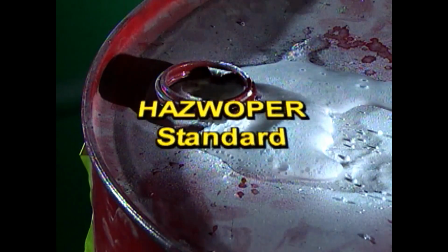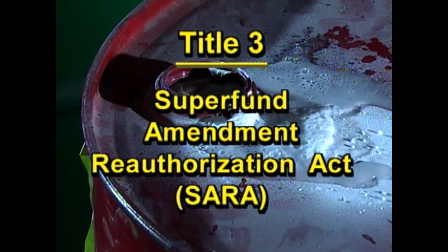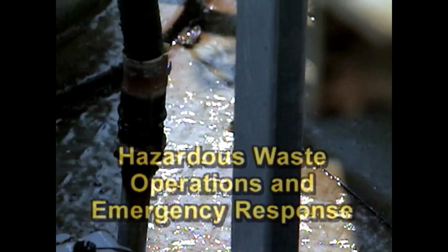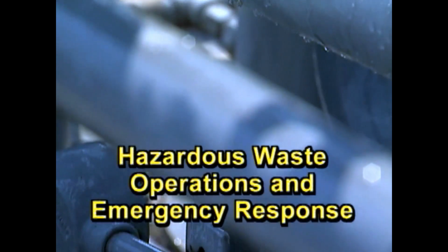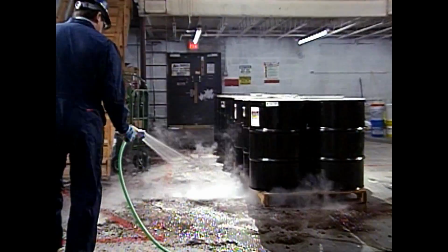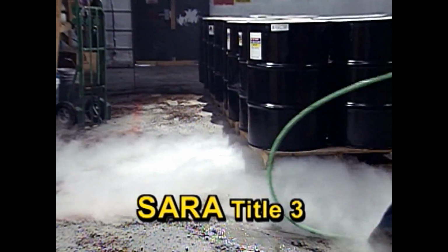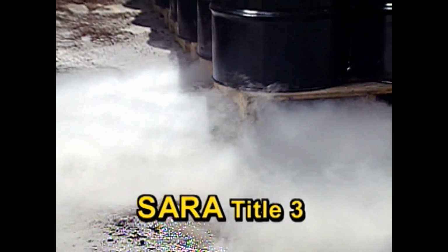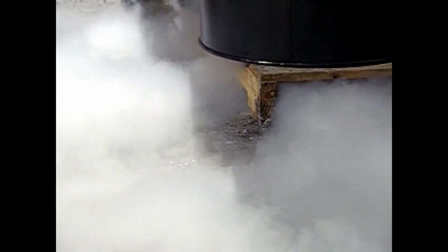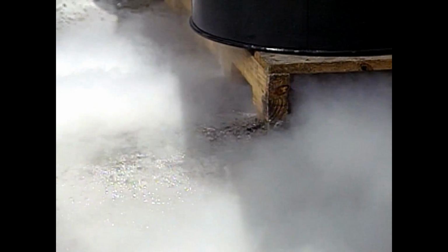In the case of spills or leaks, the HAZWOPER standard, along with Title III of the Superfund Amendment Reauthorization Act, or SARA, may apply. HAZWOPER, or Hazardous Waste Operations and Emergency Response, establishes strict training level guidelines when a dangerous spill or leak threatens your workplace. In addition, SARA Title III states that any hazardous spill that releases more than the threshold limit value, or TLV, of a contaminant into the environment must be reported immediately to local authorities or through approved notification methods.